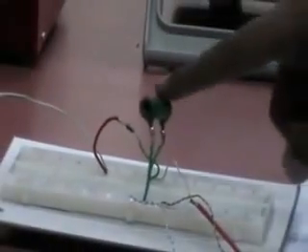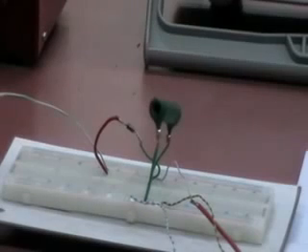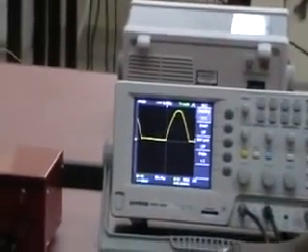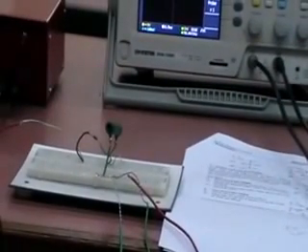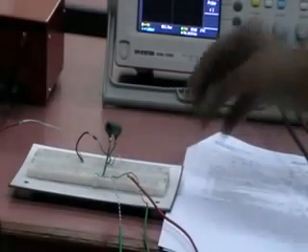In this circuit, one of the new components that we are going to see is this wire wound resistance. This is also a resistance. These resistances are mainly used for the purpose of load, because you are going to get high power as output. So these will have high power ratings, so that the resistors have high capacity to handle the power. Otherwise, if you use the small resistance that we used in the previous case, those will easily blow off.